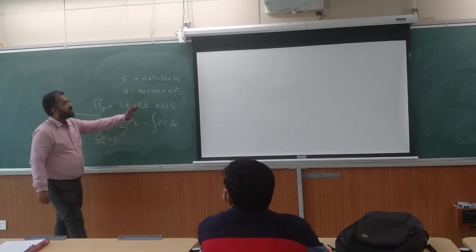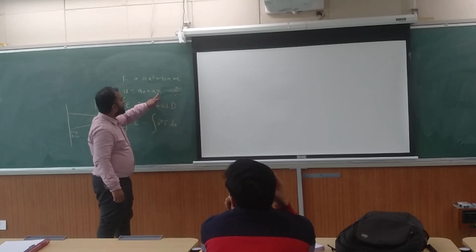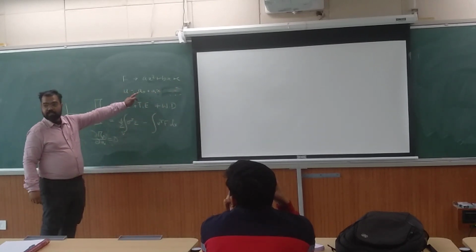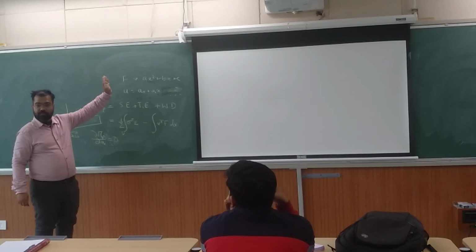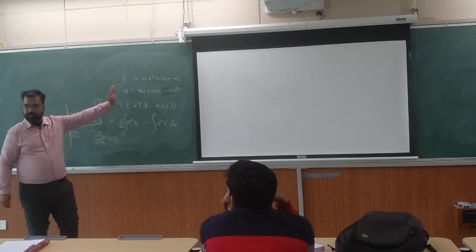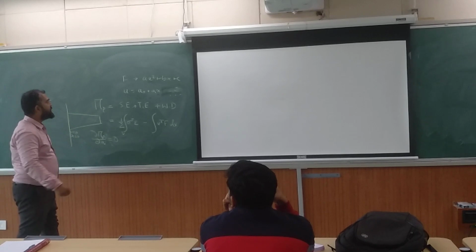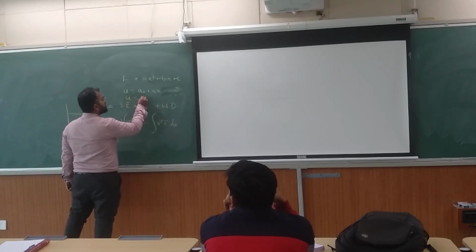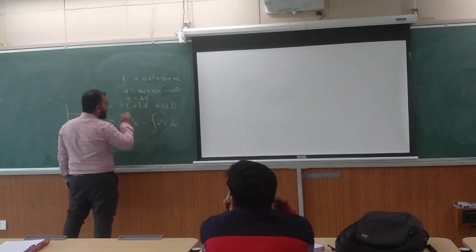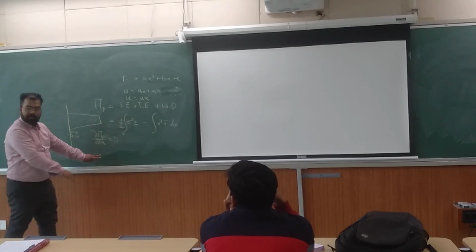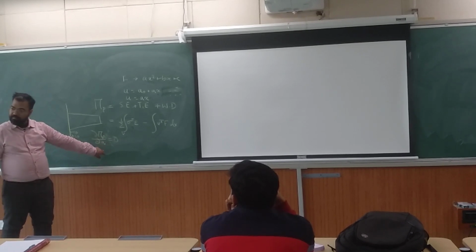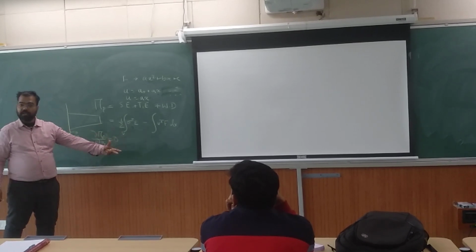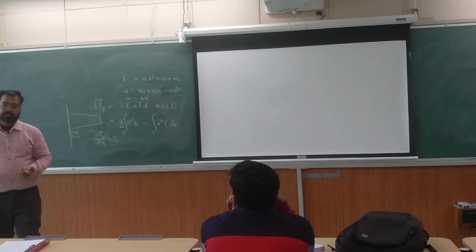So if I take only two terms and take x is equal to 0, A0 must be 0. So I can remove A0. I don't really need to solve it. Okay? So I can simply take a function u is equal to A1x and apply those in this and solve it by doing del pi p del A1 is equal to 0, and then I find out what should be the value of A1.